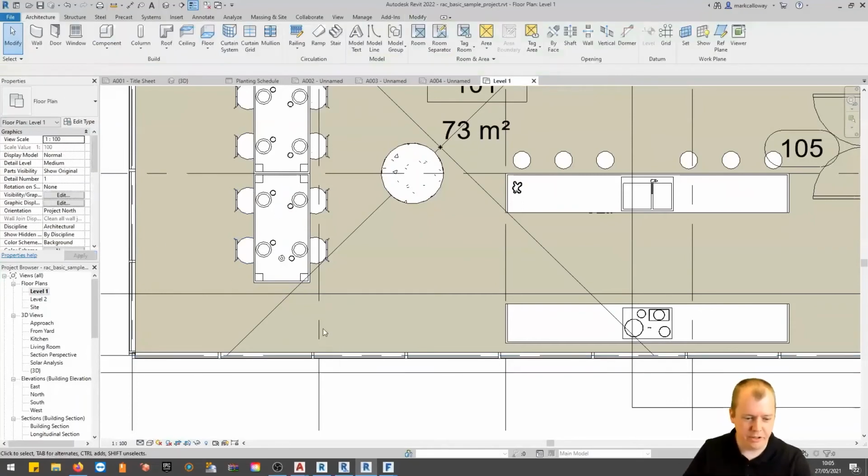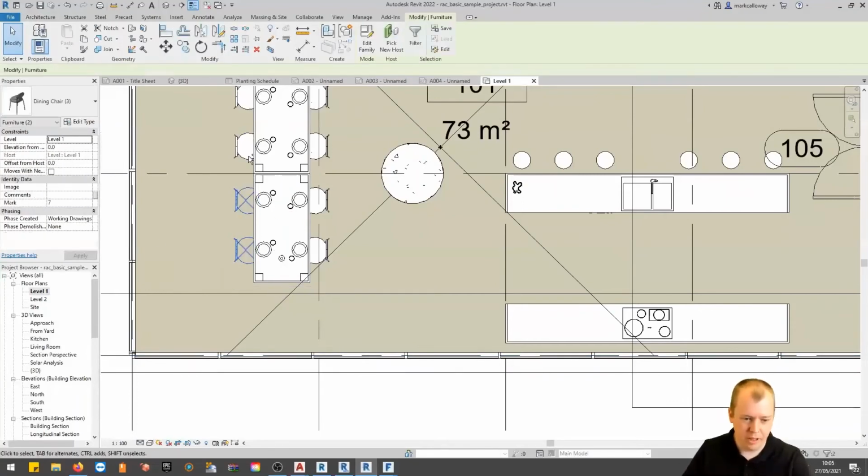Okay, that's nice until you start selecting multiple components. Traditionally within Revit, if there were multiple values, you would still just get a blank box, giving you no indication as to whether a value existed for a parameter. Now we get this Varies. Okay, so if you've got multiple selections, and this is the same for schedules as well, where you've got components grouped together, instead of it just simply giving you a blank box, giving you no indication as to whether the parameter has been completed or not, we now get this Varies text that appears. Okay, you can customize what it says in this box. You don't have to go with Varies.